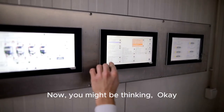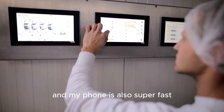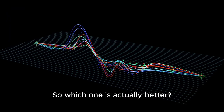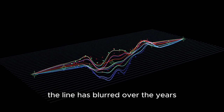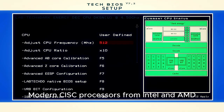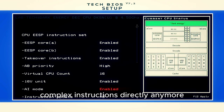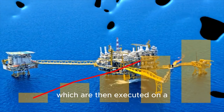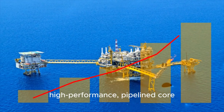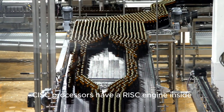Now, you might be thinking, okay, but my Intel processor is super fast, and my phone is also super fast. So which one is actually better? The truth is, the line has blurred over the years. Modern CISC processors from Intel and AMD don't actually execute those complex instructions directly anymore. Internally, they break them down into simpler, RISC-like micro-operations which are then executed on a high-performance, pipelined core. So, in a way, modern CISC processors have a RISC engine inside.